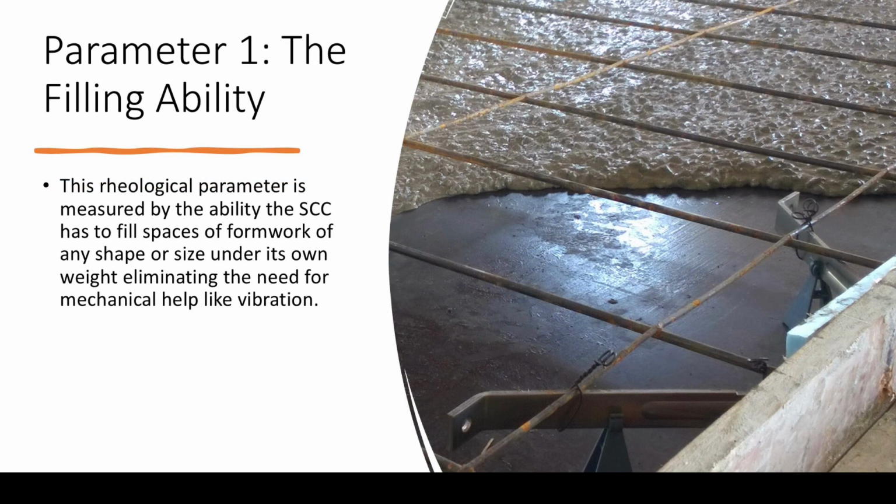First, let's talk about parameter number 1, the filling ability. This rheological parameter is measured by the ability the self-consolidating concrete has to fill spaces of formwork of any shape or size under its own weight, eliminating the need for mechanical help like vibration.